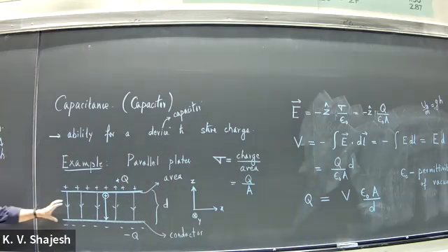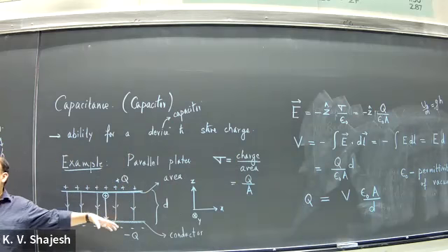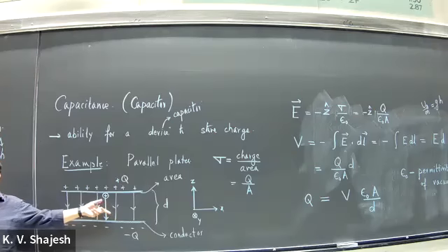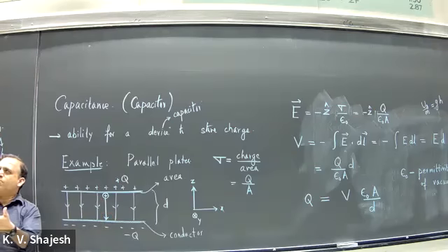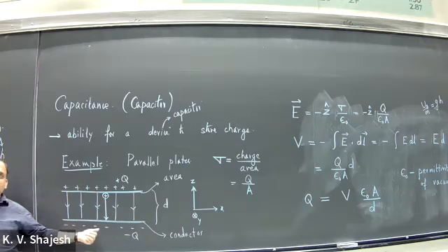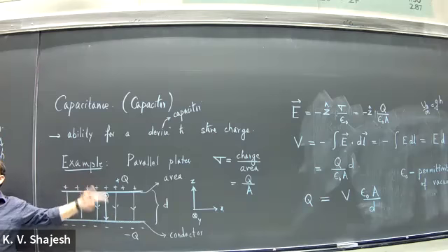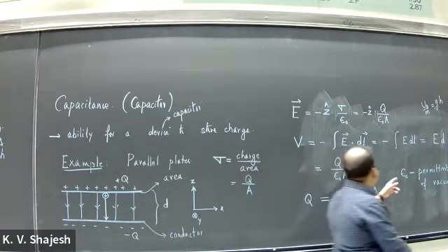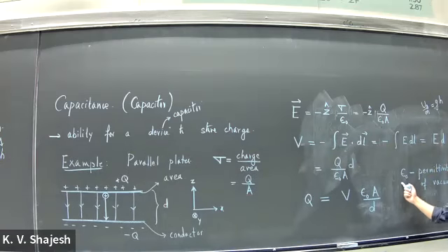So usually you use simple materials like paper, for example, is a convenient material that you can put in between two plates. It cannot be conducting, because if it is conducting, then it will short, right? Then it will immediately make the charges move from positive to negative. So you want a non-conducting material, basically an insulating material, and which will increase this epsilon naught. Almost every object has an epsilon naught, or the permittivity, larger than vacuum.